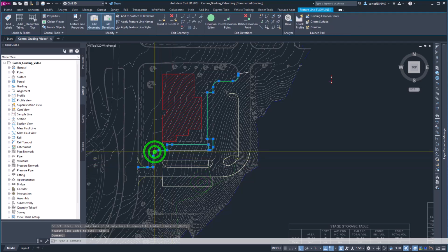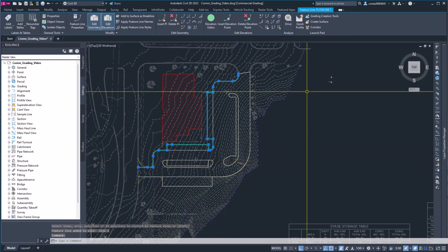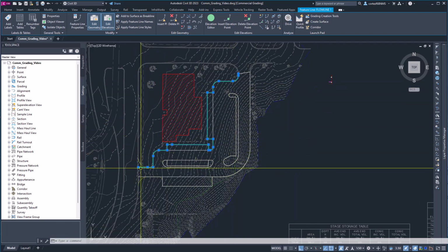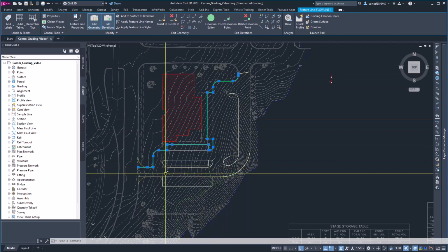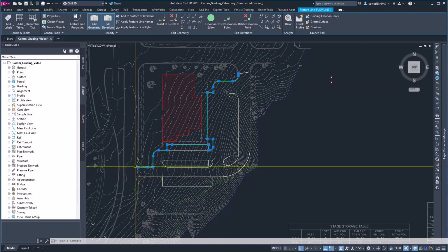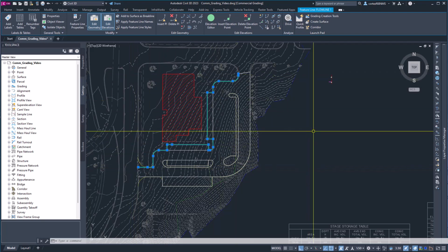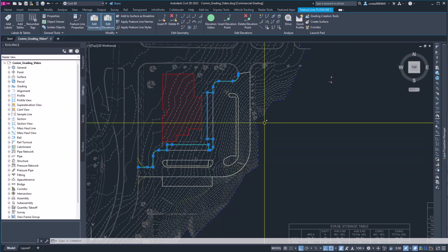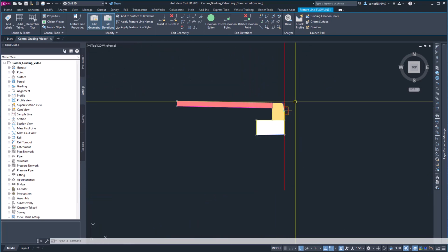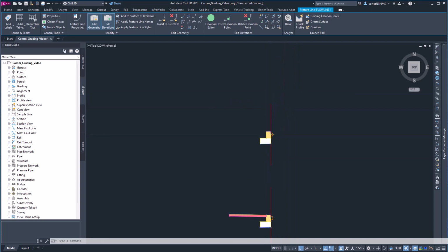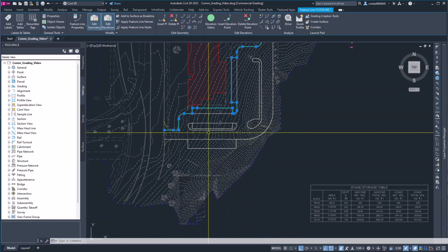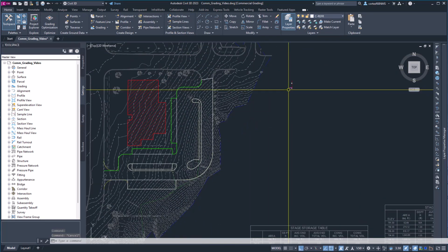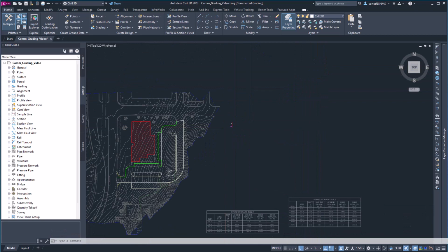And typically with this feature line, the next thing we need to take into account is the direction it is going. Typically the feature line will follow the direction in which you drew the polyline. In this case, I started here on this corner and drew it going around to there. The reason you want to take into account the direction of your feature line is because of the side that you need your curb to be on. By starting here in this corner and going in this direction, my curb is going to be on the left side like I want it.